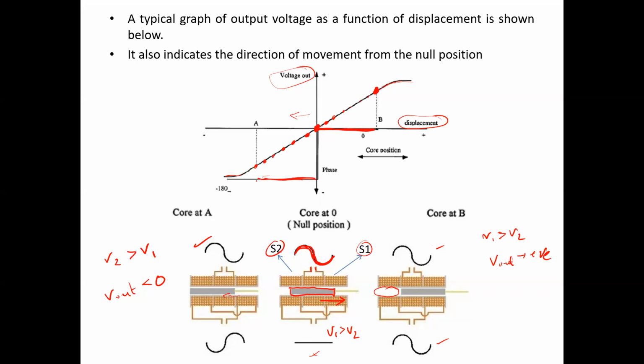So this is the general characteristics of the LVDT. Now the focus is to operate the LVDT within this linear range of operation. Then the variation can be easily predicted through the simple linear relationship between the change in displacement and the change in output voltage.